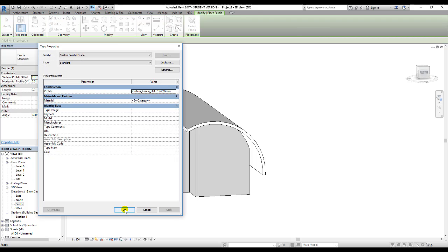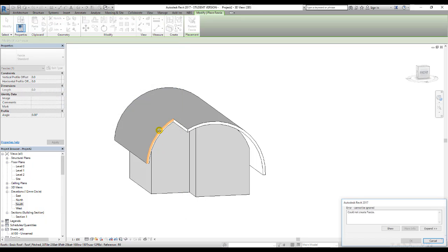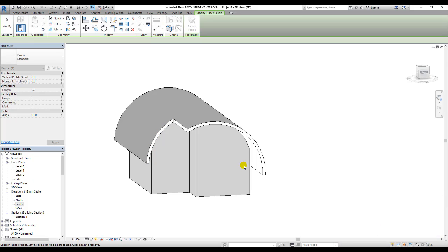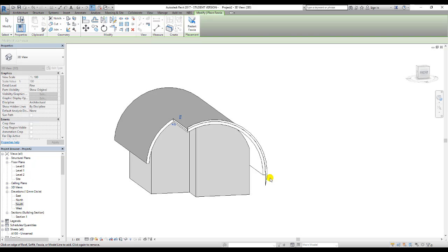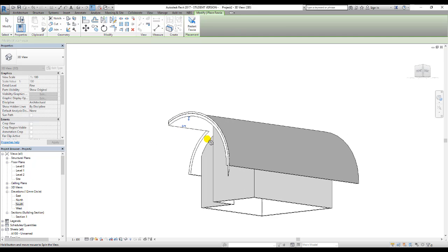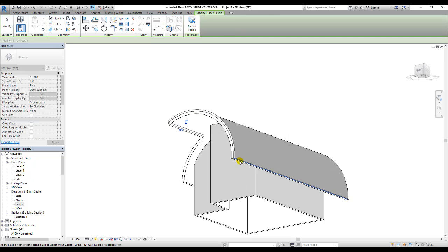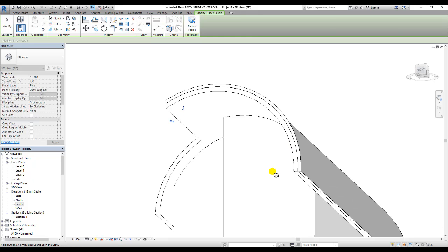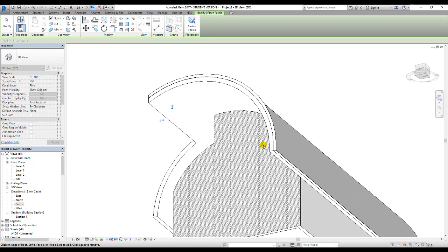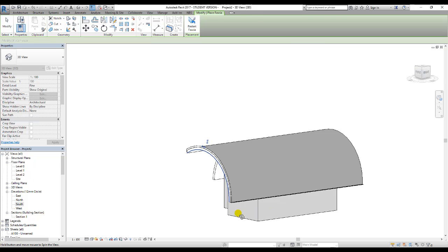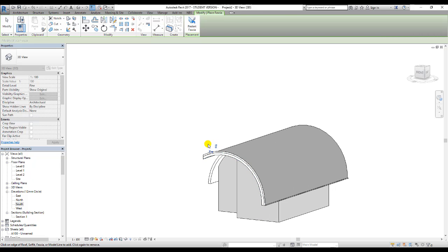Okay, the 19 by 220, and I can click on that and it forms that there. Could not create fascia. It doesn't like doing that. So again, it'll probably do that bit and it's managed that bit, but look, it's really screwed up the edge. So there are limits to what you can do. It's actually worked on that bit there. Okay, so some things to be aware of.